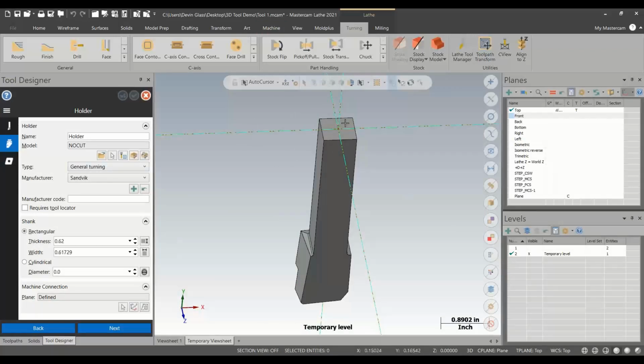The position of that is not super important. So if you have a holder that has maybe like a step down here, like maybe it's a Capto tool, I think is what first comes to mind, and it has like a step because it slides into another holder, you could pick that other back face. Orientation's all we care about in lathe, and then in mill turn, if I'm not mistaken, the position of that plane also comes into account when you're mounting it to the turret. Again, you can adjust it after the fact. That's not a big deal.